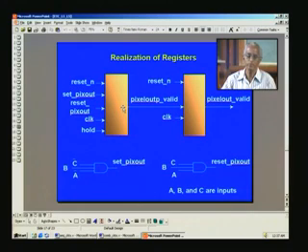In other words we want to delay one particular signal, in this case what is called pixel out valid, with a P standing for the previous value. Actually this is the real value that we are interested in, but we want it at the next clock pulse.